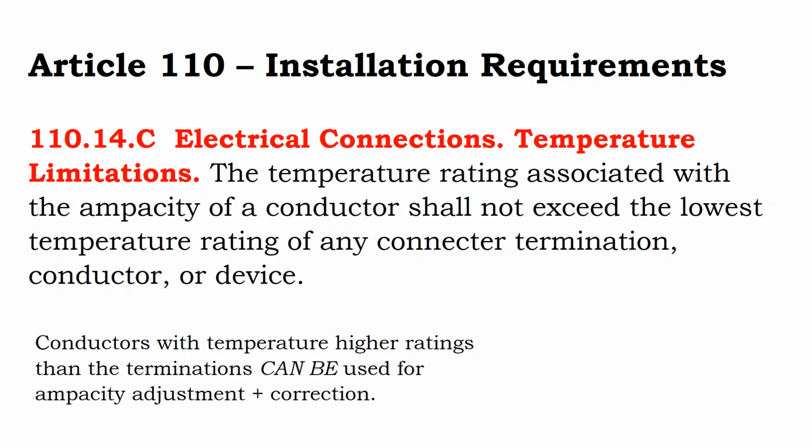So often you will find that you need a junction box or you need a disconnect switch. And maybe if you had ordered it from your solar distributor, they would have given you a solar disconnect that had been listed for a higher temperature rating because it's a solar device. But most of your utility disconnect switches are outdoor rated. They have the right voltage, the right service, and they're rated for outdoor use. You see them all the time on the outside of a building, but they're not ever intended to be placed on a rooftop, and so they're not rated at that higher temperature rating.